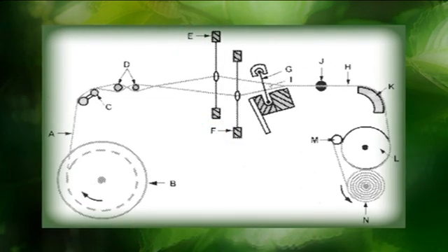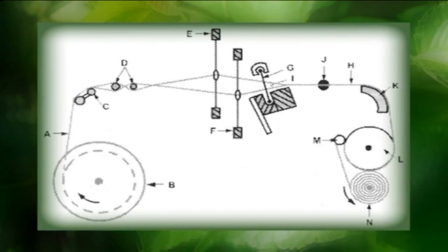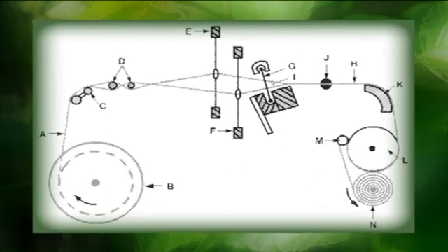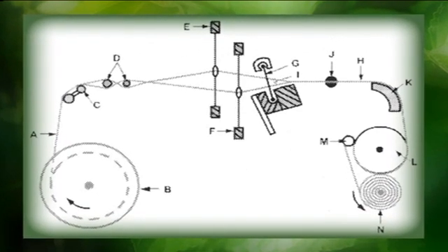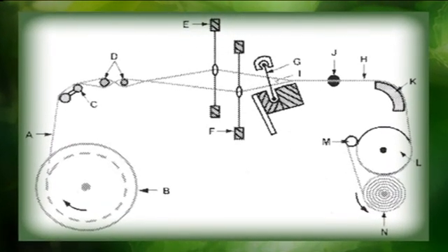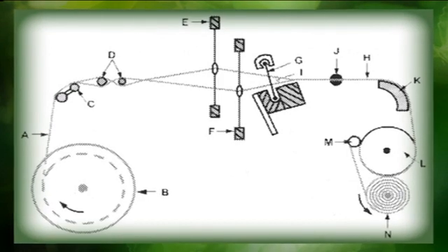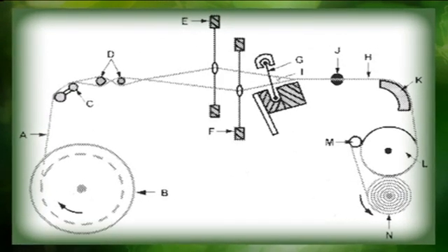The purpose of the backrest and the Lees rods is to separate the warp yarns uniformly and precisely and reduce entanglement and tension in the yarns during the opening of the warp shed.